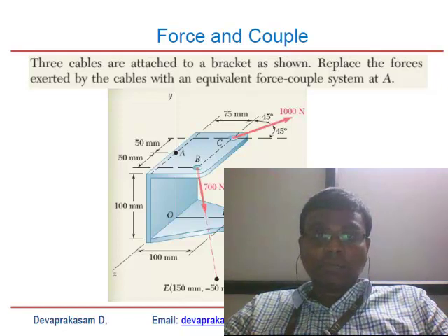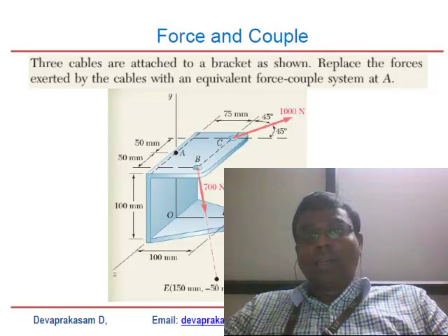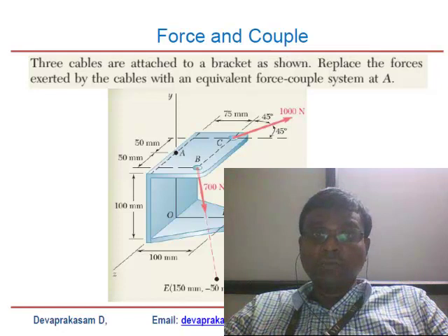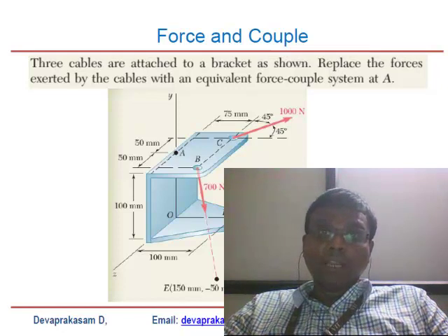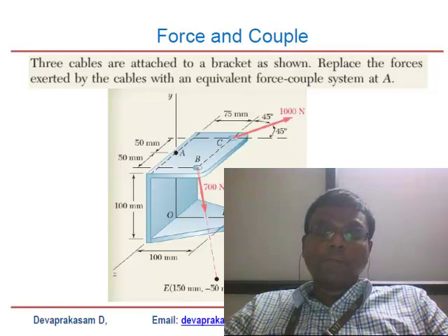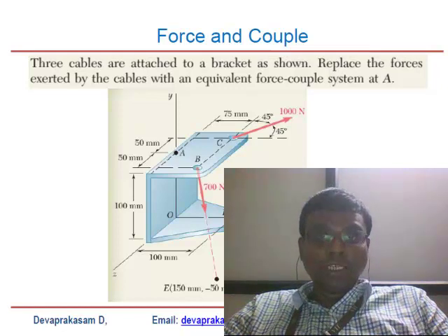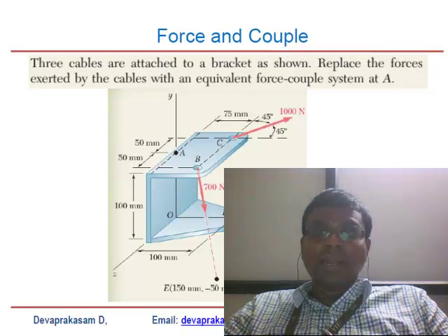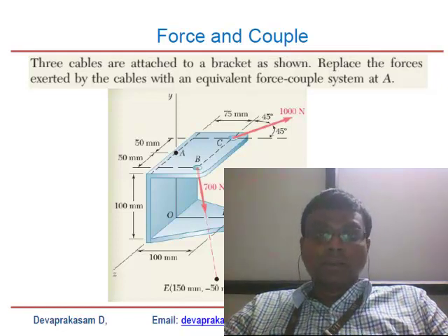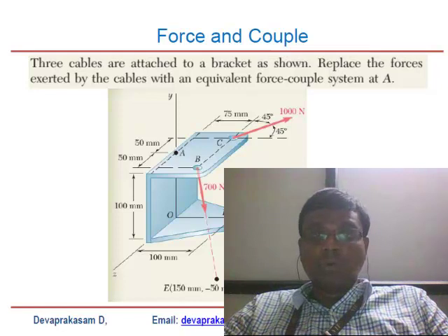You can determine the direction of that force using unit vectors, multiplying the unit vector with the magnitude of the force, or you can use the angles at which the force acts, resolving along the x, y, z axes, or you can use the slope at which the force acts.